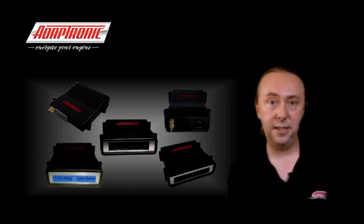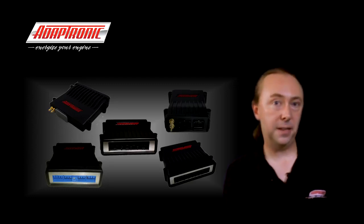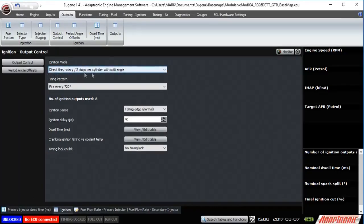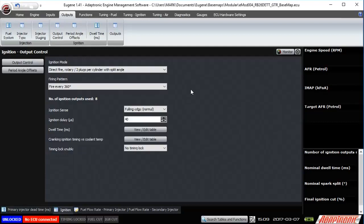From there, the first thing we need to do is set the ignition output mode. For a rotary, or an engine with 2 spark plugs per cylinder, there are several different modes that we can use. Direct fire rotary / 2 plugs per cylinder is the default mode that you'd use if you're running a single coil per spark plug. In this mode, you must select the firing pattern as well, which will need to be 720 degrees if you're running a piston engine with 2 spark plugs per cylinder, or more commonly 360 degrees if you're running a rotary.